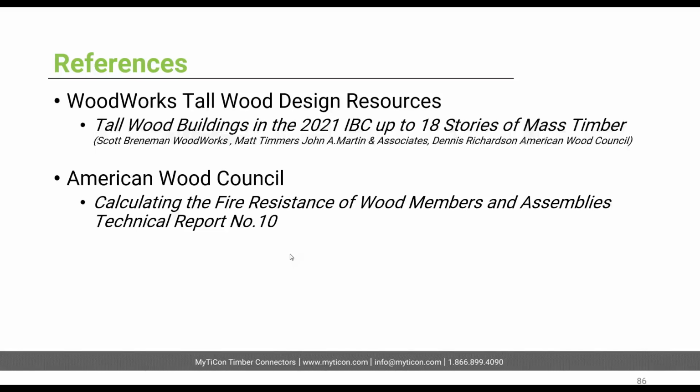So other questions are asking if it was certified for 1.5 hours, how we did the 2 hours. It was certified for 1.5 hours, but the 2 hours in the tables were actually using the NDS and the codes. And again, I mentioned by providing enough char thickness and wood cover at the bottom, you can achieve that 2-hour fire rating. And you don't need to add extra wood members.